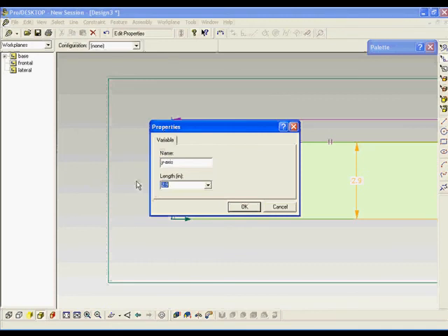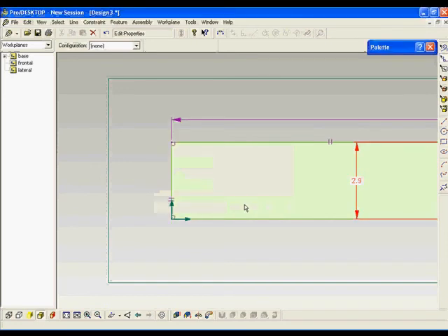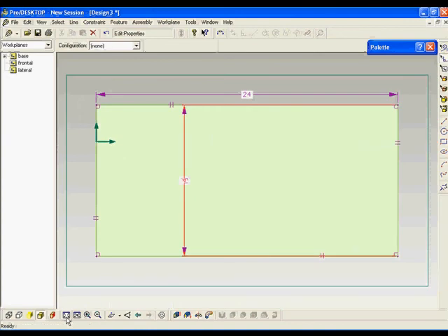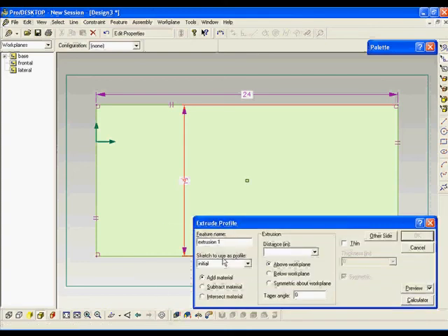So now my rectangle in my orthographic view has become a 12 by 24 inch rectangle. Now I'm going to convert the 2-dimensional drawing into a 3-dimensional pictorial drawing by adding material in the Z direction of 8.25 inches thick for my van body.